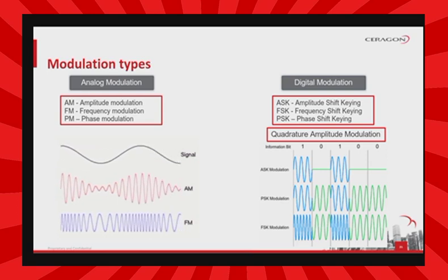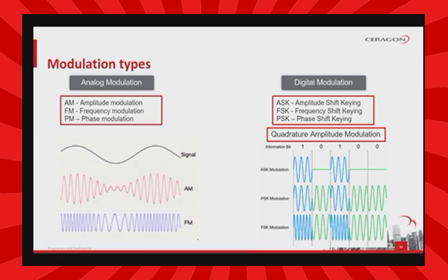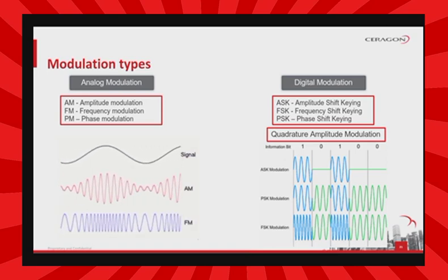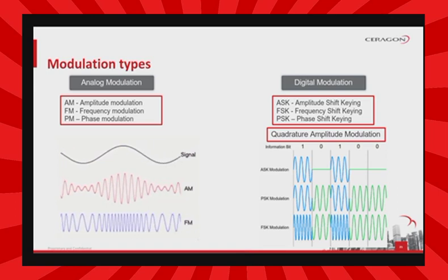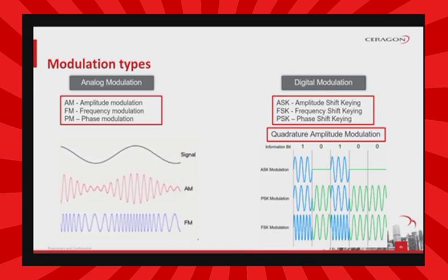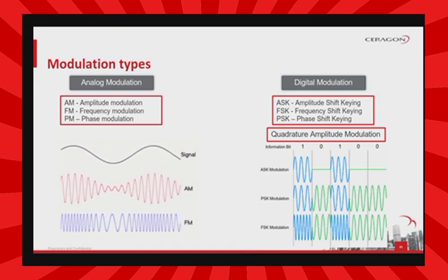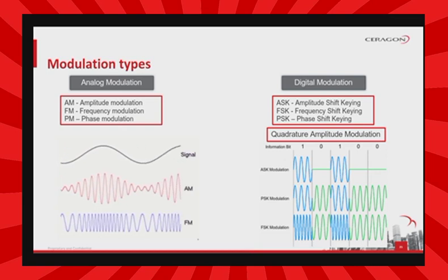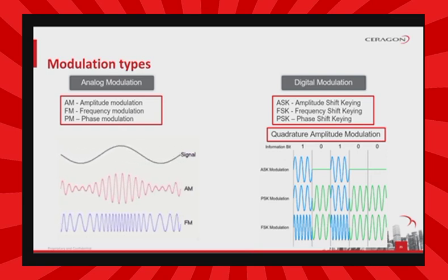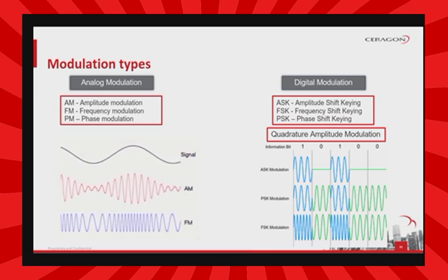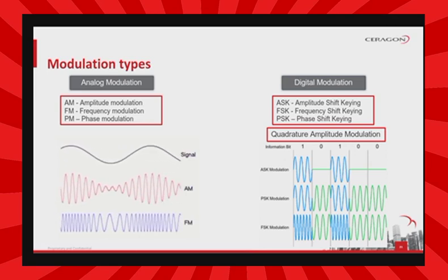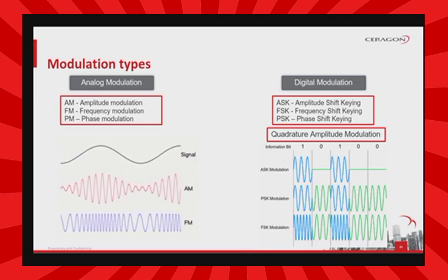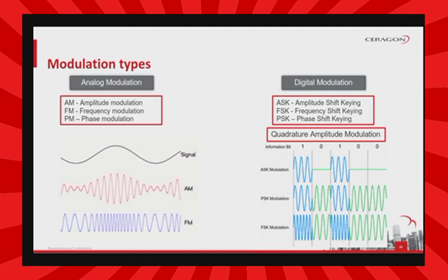Amplitude modulation is a method of impressing data onto a time-varying signal carrier waveform, digital signal in our case. The highest frequency of the modulating data is normally less than 10% of the carrier frequency. QAM is a method of combining two amplitude modulated signals into a single channel, at a quadrature shift or 90 degrees between them. The modulated signals are summed, and the final signal is a combination of both phase shift keying and amplitude shift keying. QAM is, simply said, a combination of amplitude and phase modulation for transmitting more data, easier.